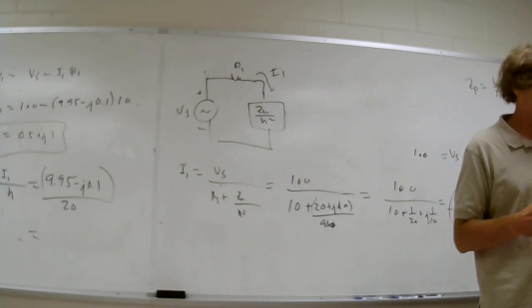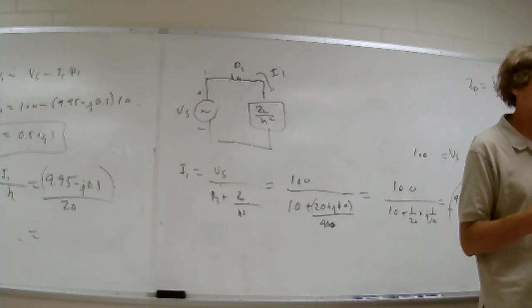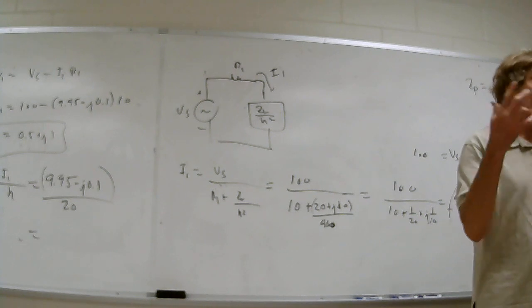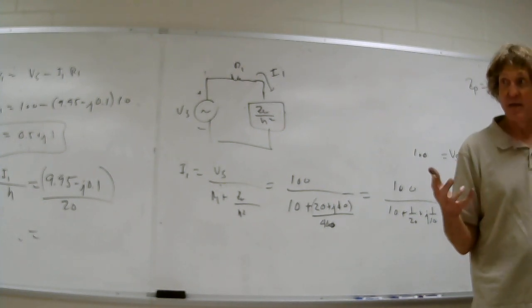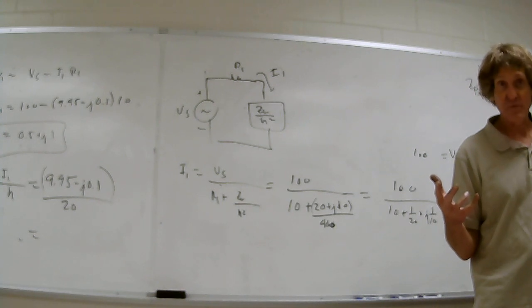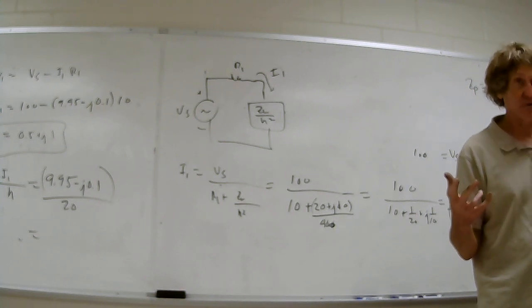We used one to charge up some capacitors for the railgun with the 10,000 volts. We had to create a full wave rectifier on the secondary that could withstand 10,000 volts of reverse voltage, and that was with some clever diodes. Wow.